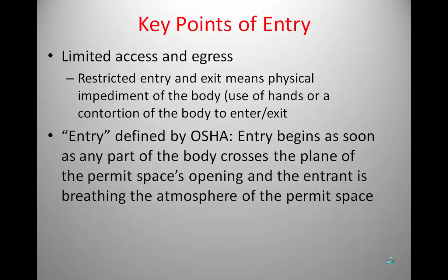A lot of times it's very easy for an attendant or one of the riggers to become technically defined as an entrant. If he or she is helping out around that space and has to put their body into that opening to, say, manipulate somebody's harness that's hung up on the space's ladder area, or a common one, if you're wearing the escape bottle, sometimes that escape bottle may have to be manipulated to a degree so it doesn't get caught. So just be cautious if you're one of those attendants or riggers during this process. Technically, if you break that plane and you're breathing that atmosphere, OSHA considers that an entry.